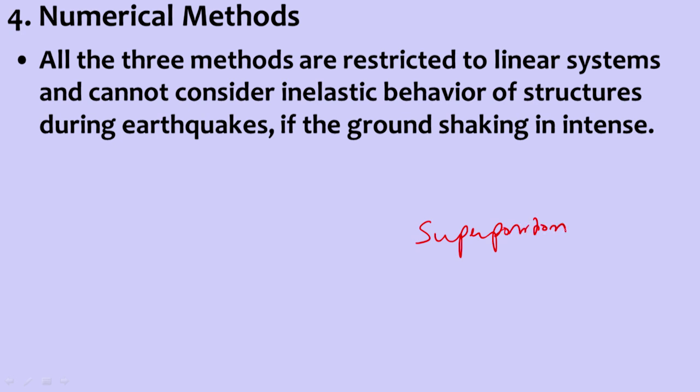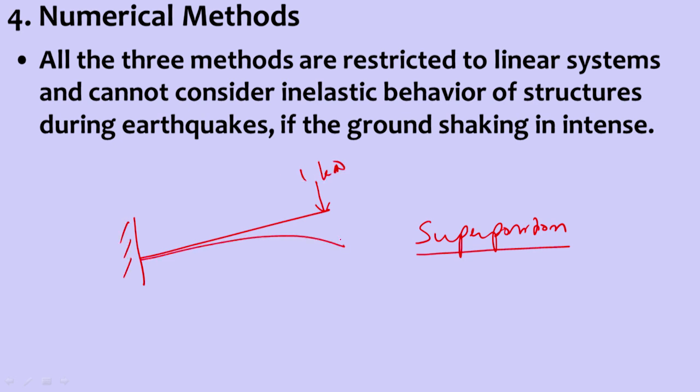The principle of superposition says, for example, if I apply a load of 1 kilonewton and I get some deflection, and later I apply a load of 2 kilonewton and I get some deflection, and later I apply a load of 3 kilonewton and I get some deflection, then all these loads put together, 1 plus 2 plus 3, if I apply all at a time, I get the same total response. That is the principle of superposition.